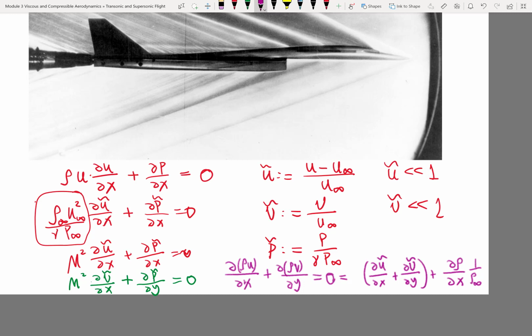That also means the shocks are infinitesimally weak, and the stagnation pressure loss across the shocks is also going to be very small. What that means is isentropic assumptions actually work here. So d rho over rho would be equal to 1 over gamma times dp over p, right? That's our isentropic relation on fractional sensitivities.